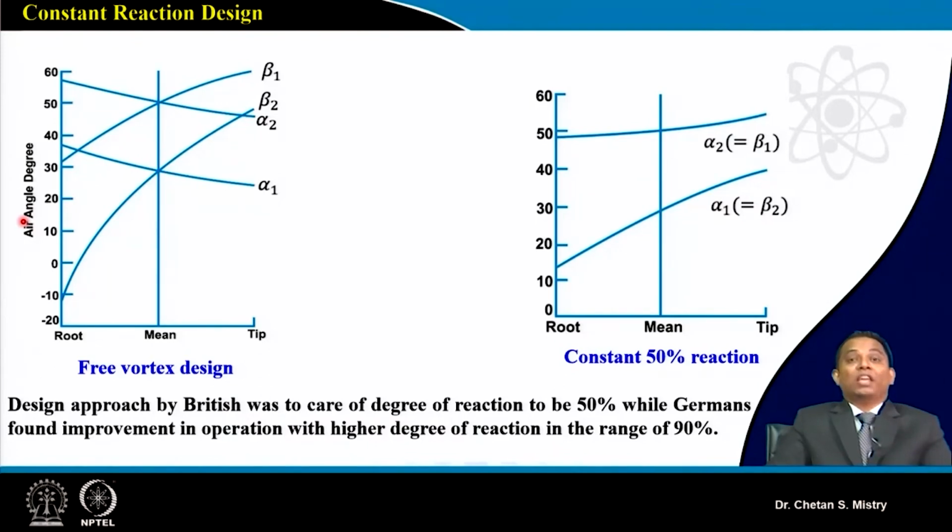Okay, and we have seen if my blade is highly cambered, suppose my delta beta is large near the hub, there are more chances for my flow to get separated from the suction surface. And that's what we have defined as a stall. And as I told, people define that as a hub stall.